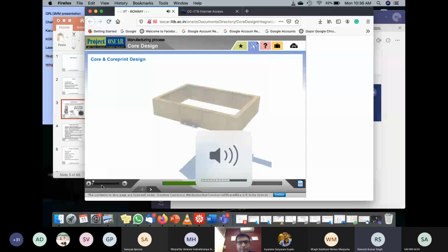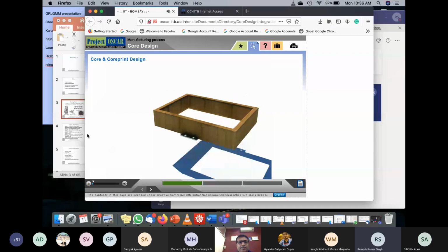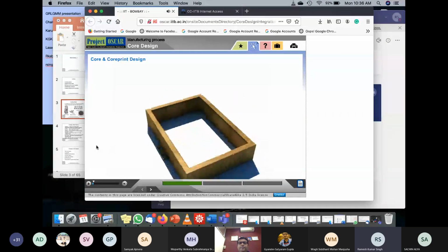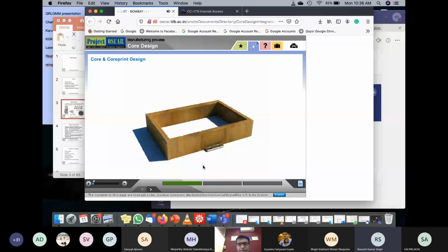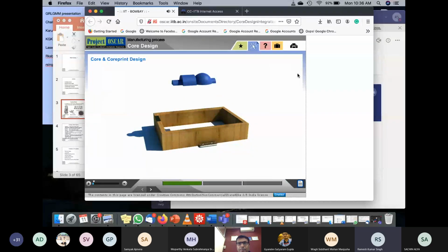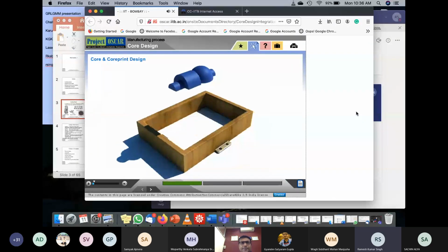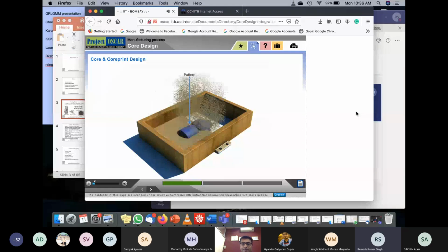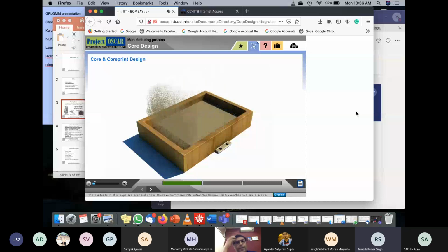This demonstration provides a useful understanding of the following steps. Take hollow rectangular boxes called cope and drag. Place the wooden pattern as shown in the animation. Fill with sand in layers and ram for equal distribution of sand and compactness.